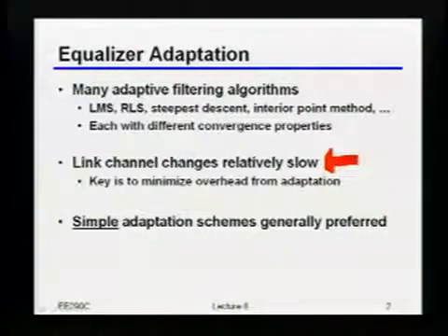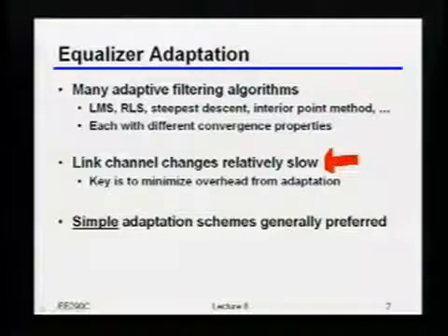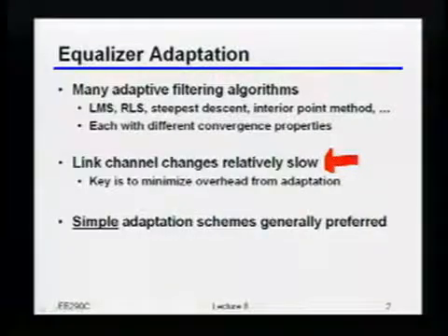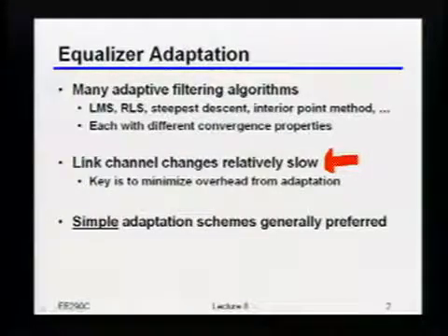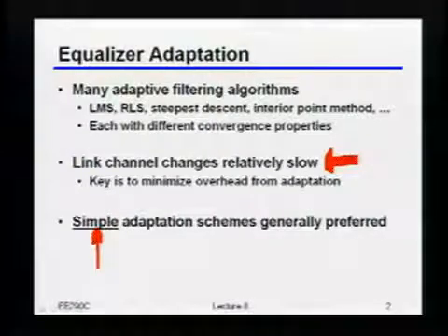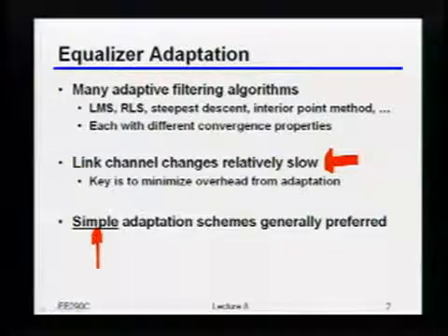That's what I'm getting at: in many link usage scenarios, you may not care that much. There are some scenarios you can come up with where you would, say a circuit-switched router where you're physically looking at different channels at different times. But in most electrical link scenarios, the convergence time is not a big criterion. Because of that, simplicity tends to be the number one constraint, simply because you don't want to spend a lot of power, and pretty much anything complicated quickly ends up adding a lot of power to your system.